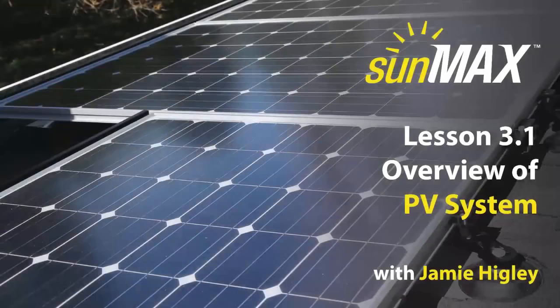These cells are connected in series to form a PV module, or PV panel, and produce a power rating relative to factors such as cell efficiency, material, and more. The collective group of panels that make up an entire solar energy system is called the PV array. The junction box, located on the back side of the PV module, is a protective terminal enclosure for current-carrying conductors to join the panel.